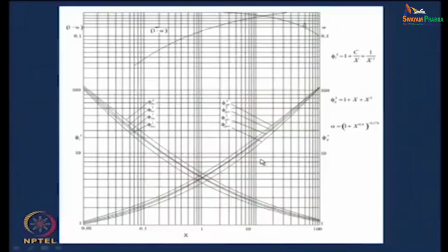Okay. Now, you just remember certain things. This particular correlation which I have shown you is used specifically for horizontal flow without phase change. So, therefore, it is more preferable for air water flows, for steam water flows. It has not been derived for that particular situation. The correlation was specifically derived for horizontal flow without phase change or significant acceleration, and it can be used to calculate both the void fraction and the frictional pressure drop, even when these effects are not negligible also. It can be used. Okay.